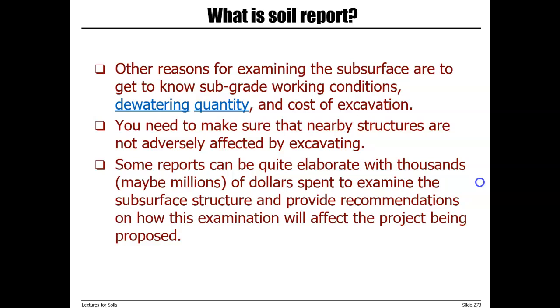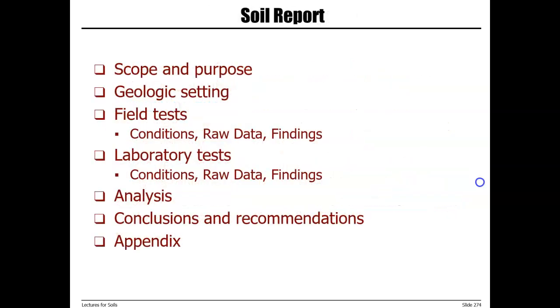It really depends on how big the project is. Some reports can be elaborate with thousands of dollars spent to examine the subsurface structure and provide recommendations on how this examination will affect the project being proposed. So in a soil report, you will see the scope and purpose of the project, geologic setting, field testing, including the conditions, raw data and findings, laboratory testing, analysis, conclusion, and recommendation.